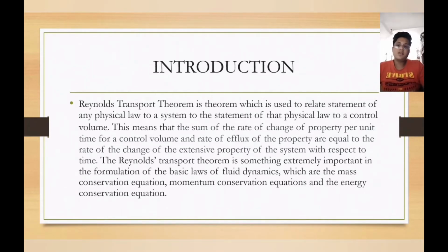This means that the sum of the rate of change of property per unit time for a control volume and the rate of efflux of the property is equal to the rate of change of the extensive property of the system with respect to time. The Reynolds transport theorem is extremely important in the formulation of the basic laws of fluid dynamics, which are the mass conservation equation, momentum conservation equation and energy conservation equation.